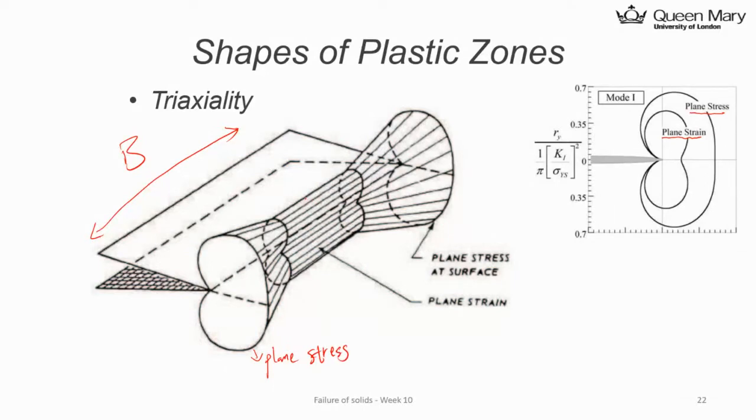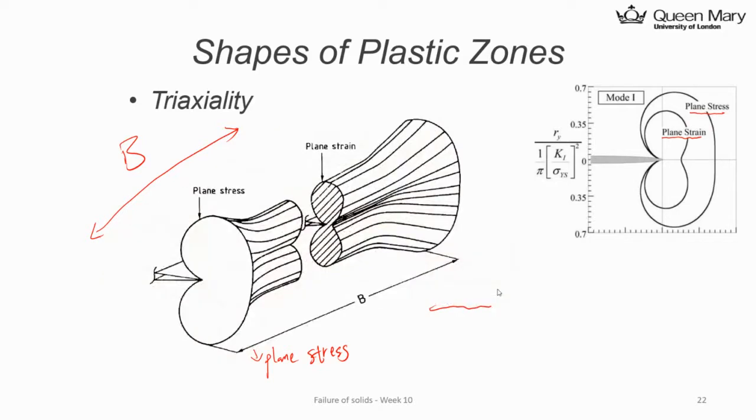And inside the material, now you can see the peanut shape for the plane strain condition. Another figure which is more clear to show this is like that, okay? This is showing I cut a cross section at the center of the material, somewhere here. Now I can see the plane strain is giving me the peanut shape. Outside is still a broad beam shape. Okay, everyone understand that?